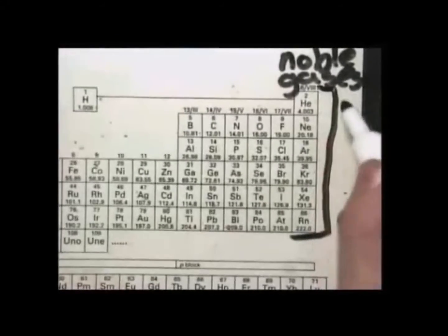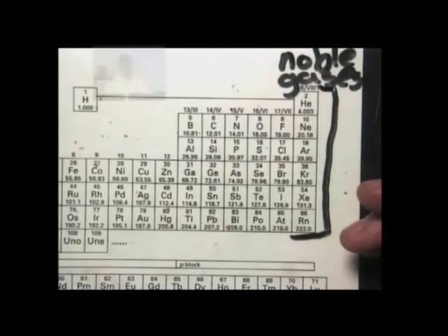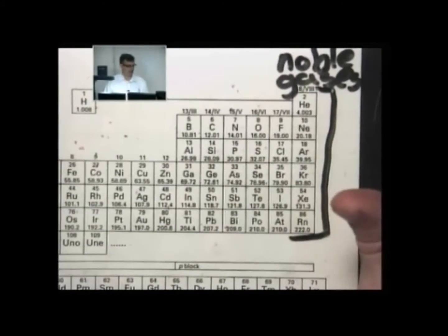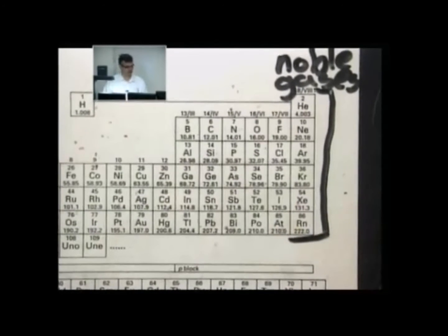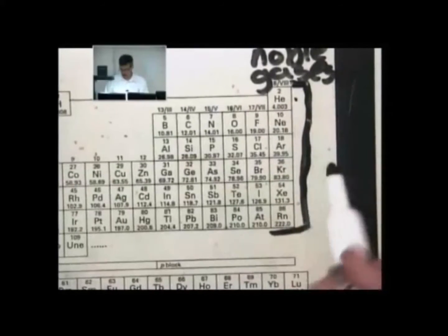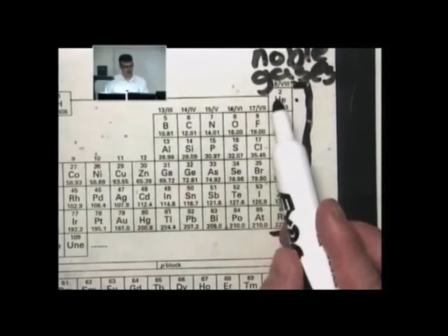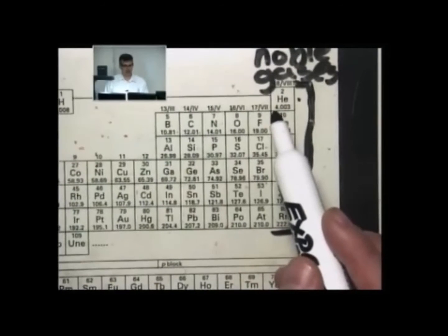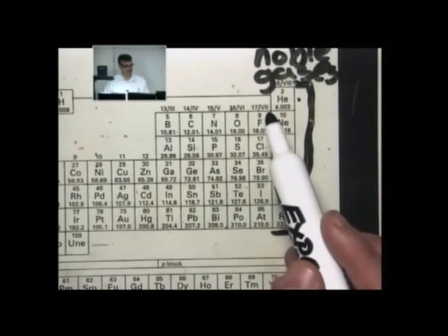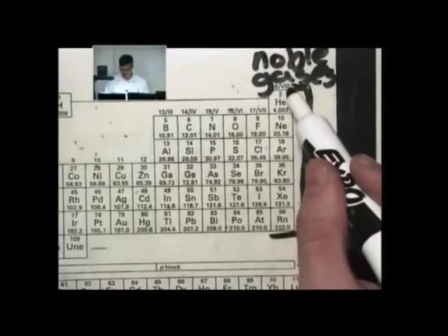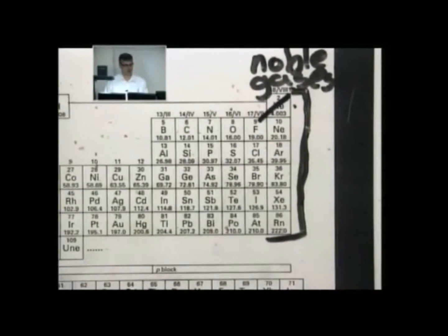So these are gases. However, the nice thing about the gases is that under relatively reasonable temperatures and pressures, we can liquefy them and put them in a tank. So if we had to carry a giant balloon into space, these wouldn't fly. But of course, these can be stored compactly under reasonable conditions. And really, it comes down to picking one that has a high enough mass to use as a propellant. The higher the mass, then the more momentum we can impart to it and use as a propellant. So, of course, helium is off the table because it's just too light. It's 2 protons and 2 neutrons.